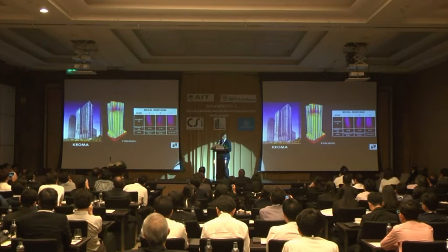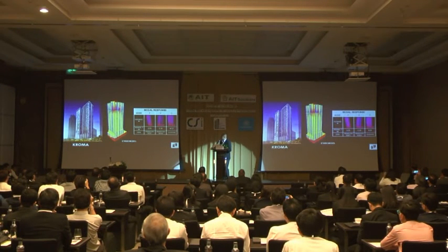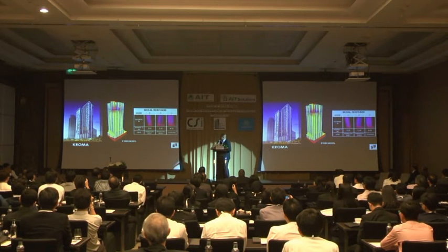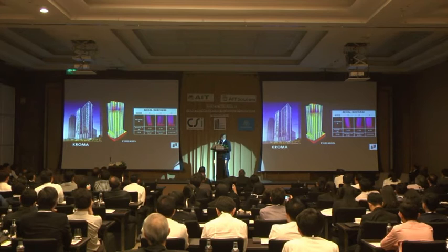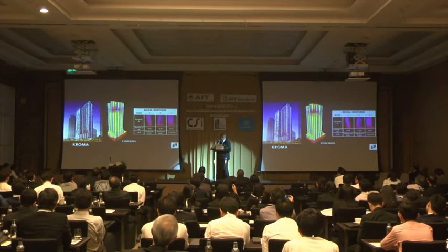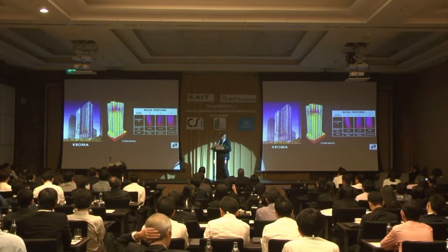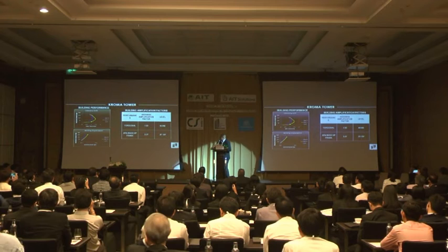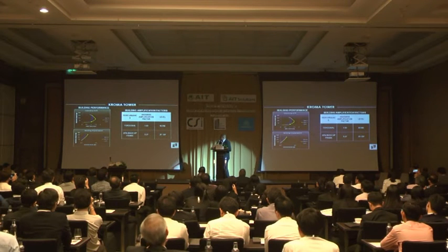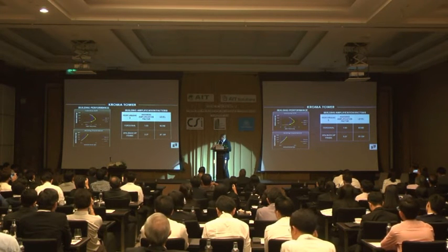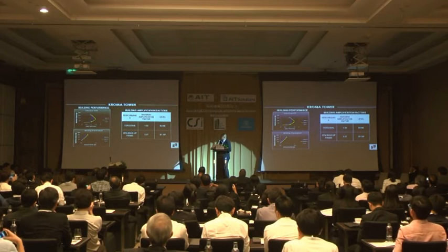Next is Chroma. Chroma is a 146-meter tall structure with 48 stories. So the mode of response is translation in y-axis for the first mode, and also the translation for x at the second mode. The third will be rotation. Next, please. So in this case, only the penalties for the third to 10th floor for the 25% backup frame.